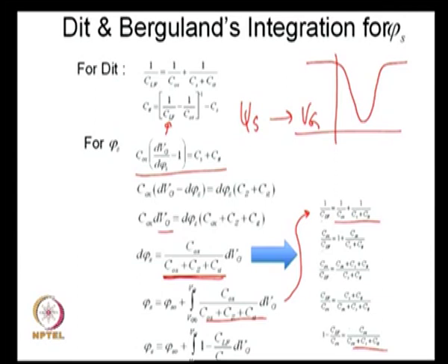CLF is what is measured externally, and Cox can always be obtained because it is the accumulation value of capacitance, so you can find out what Cox is. In other words, this term inside the integral can be replaced by 1 minus CLF measured divided by Cox.